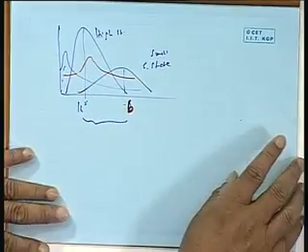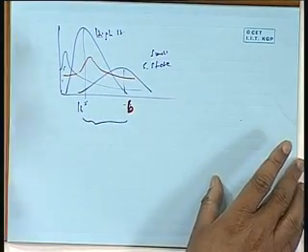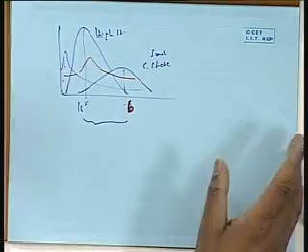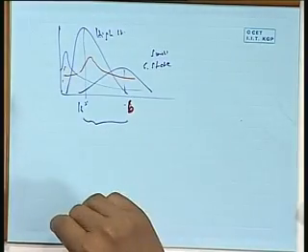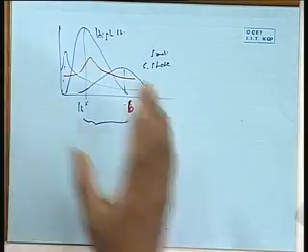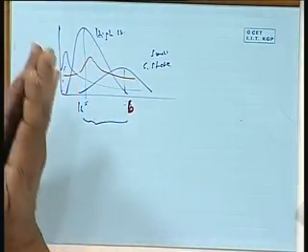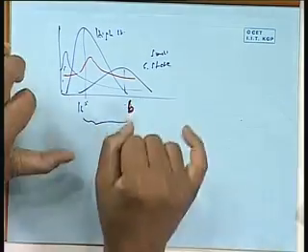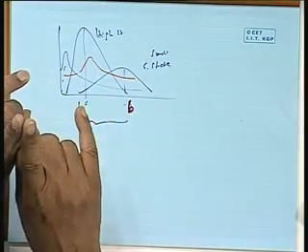So if you take a barge with a high GM, then it has got a low natural roll period, and even in the smallest wave it is going to have a very large roll. So it is not comfortable. So this tuning is very important in any motion, and that's why I mentioned this, because it turns out, unfortunately for ships, that the natural periods are not widely far from the kind of peak period of the waves that occur.